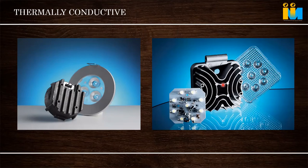Because when we glow an LED, at the bottom backside of the LED there will be heat generation, 80 to 90 degrees. If we are expecting a better life for the LED, that temperature has to be dissipated fast. If you accumulate that, the LED light will come down. If I'm not removing the heat, the LED will blow off within 6 months. If the temperature management is done properly, then it stays for 3 years, 4 years, whatever it is. This is how it has been designed.